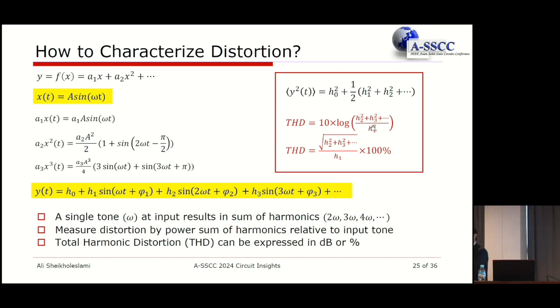You notice that this is like the inverse of what we defined for SNR. In SNR, we defined signal divided by noise. For I don't know what reason, we decided to use the opposite polarity here. So the total harmonic distortion is the power of the harmonics, which is unwanted, divided by the wanted signal. Which portion of your signal is bad? Maybe this is a better characterization of actual distortion, because your signal is what you have, and you want to compare it against your signal. So when you have a larger total harmonic distortion, that means it's worse. You have more distortion.